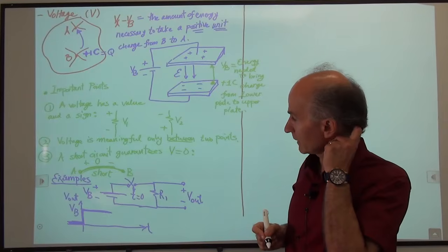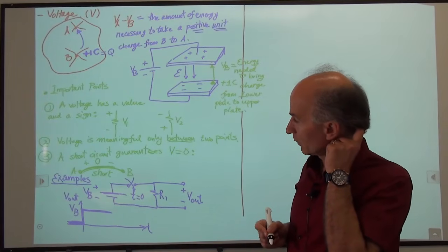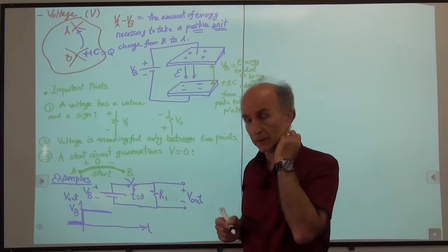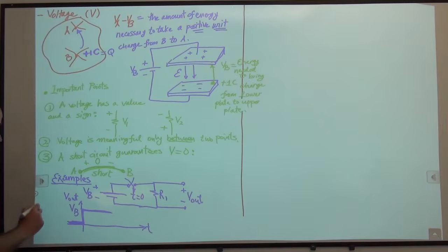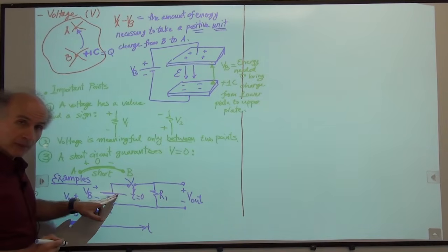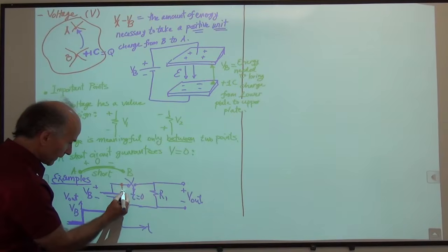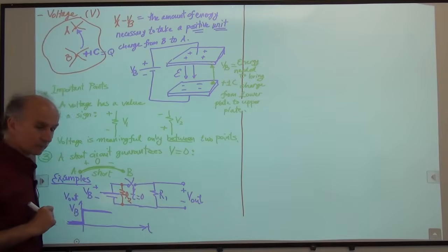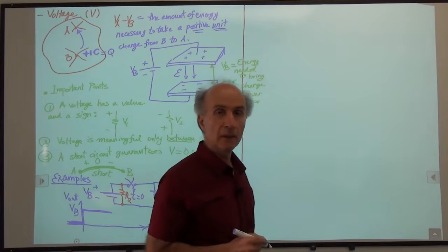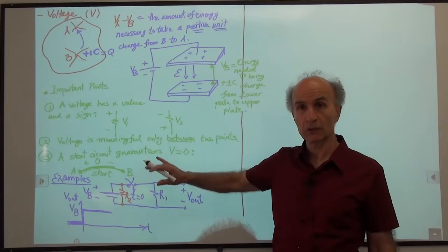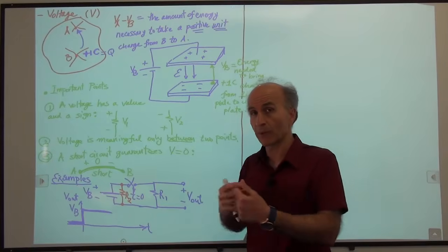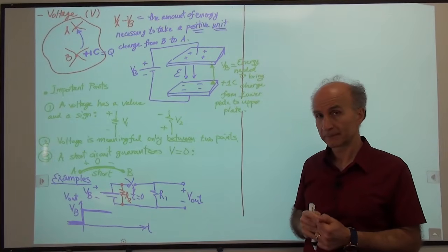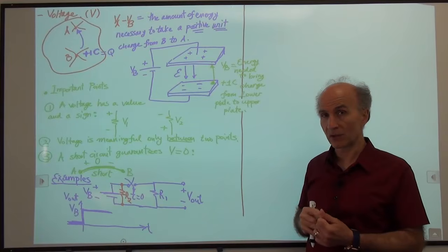Okay, but now let's decide on one interesting twist to this circuit. Suppose I go and do the following. I have this battery, and I will connect a resistor from here to ground. Call this R2. All right? And I would like to repeat this experiment. I would like to plot V out as a function of time now that R2 is present in the circuit as well. How does V out change in this case?